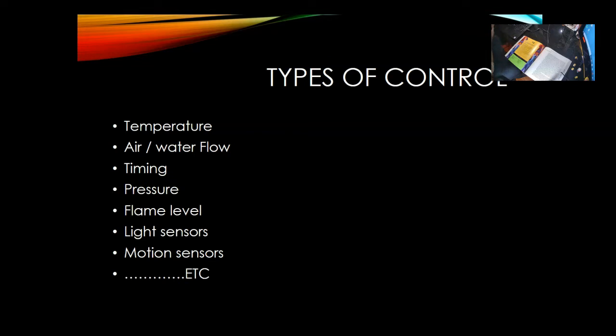This will go to the aquastat if you have a hot water system, and we will ask the aquastat to heat more water to supply heat, and this information will transport all the way to the burner and will turn on your heat. So again, it's a process of input and output. And by doing so, probably you have realized that you need three things: input, process, then output, to keep things under control.